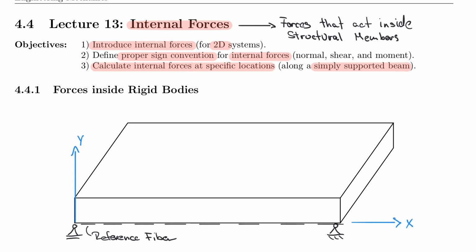But now to get to that point, what internal forces are, let's think about the fact that these internal forces are really the glue that keeps the thing together. And what do engineers do when they want to find forces? They pretend that the force is not there. So in the context of this table here, what I can do is I can just cut it, in this case, in 3 individual pieces. And let's just pretend I do it this way. And then when I separate them, what I did, I actually released forces that are inherent to the system when the rigid member is connected.